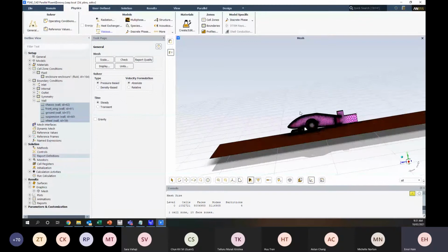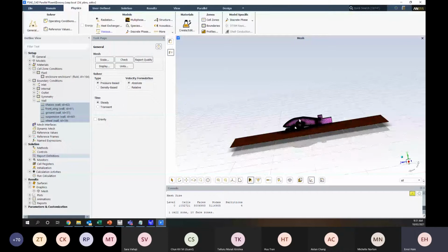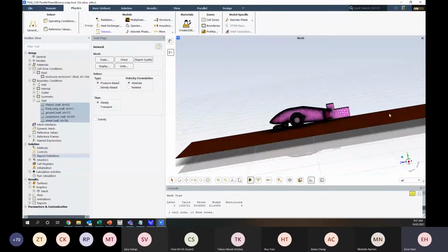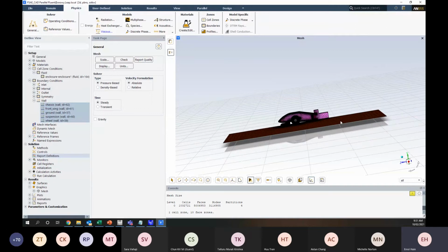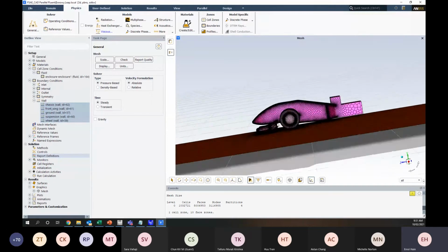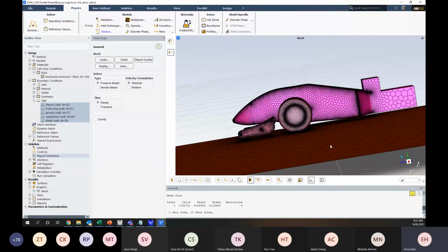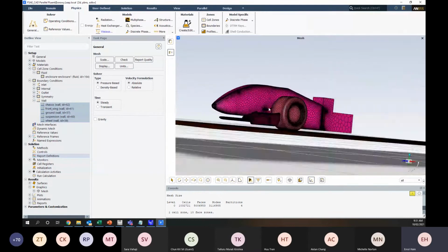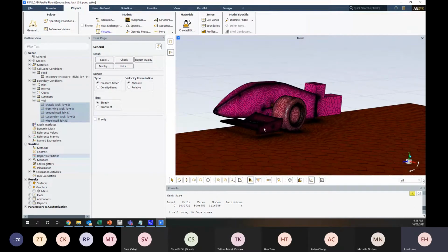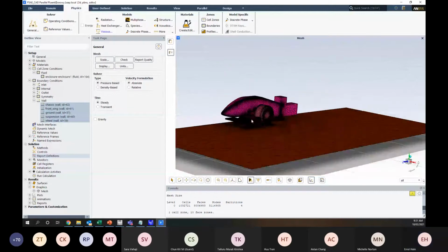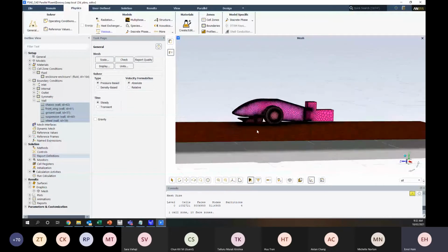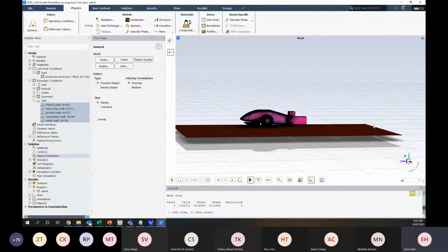Once again, that is really a trial and error process a lot of the times. It's nice to have 4 or 5 body lengths behind the object. In this case, it's probably not as big as what we would like to see, but we are really only interested in the front wing. So one of the things this model would be built for is just to assess the front wing. We might put a bunch of different front wings in there with the same chassis and the same front wheel to get a good understanding of the performance of that front wing. Because it's only the front wing that we're really interested in, we're quite a few body lengths behind that front wing. But once again, it's a trial and error process.